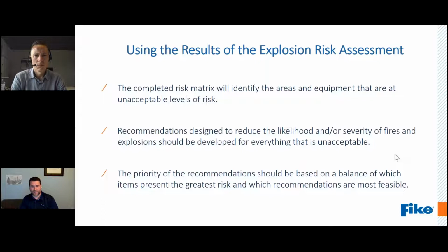I can use the example of those pictures from before with the dust and the electrical equipment. Let's say you have a location designed as a zone 22. All of your electrical equipment is zone 22. You've got the certifications, you've got everything for that. But now, through a process change or problems with the operation of the product, you've got dust accumulations, leaks, dust clouds, and now it's a zone 21.